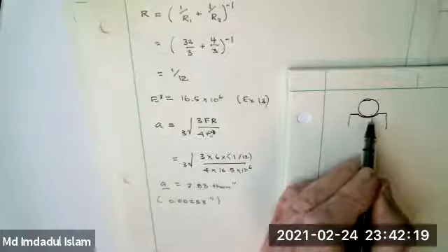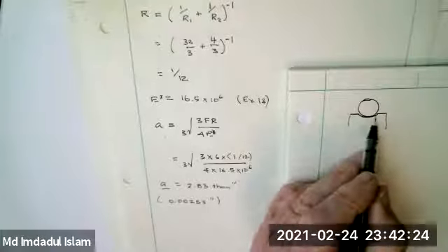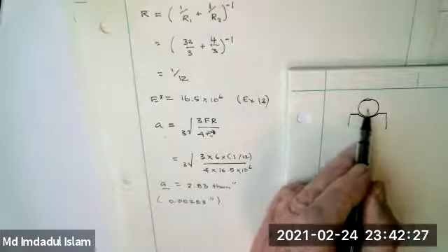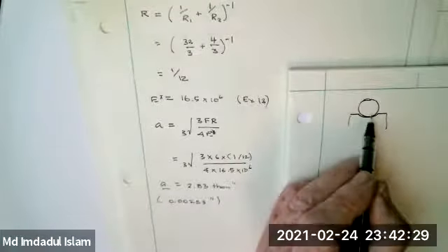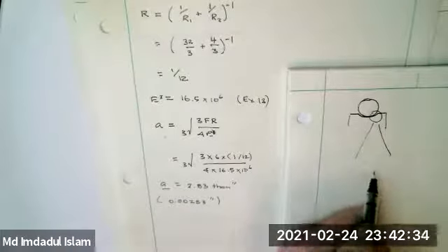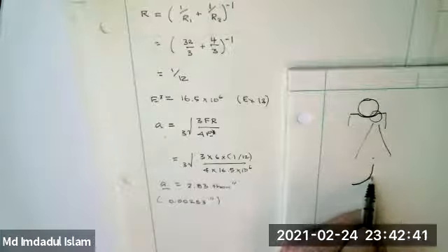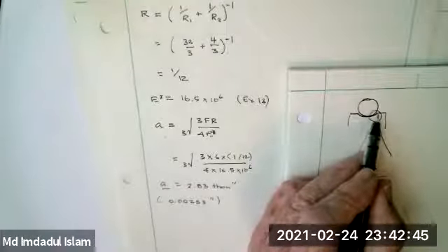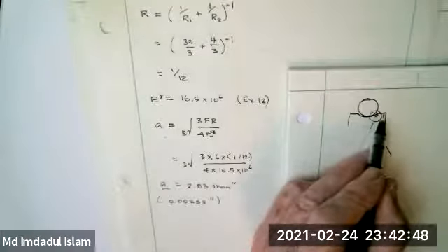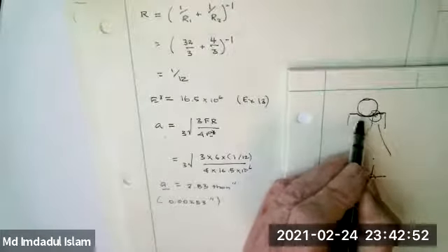Okay, what will happen here is I'll put this groove in, and this groove is shaped with a very similar radius to promote contact. But they'll design this carefully. So what happens here is there'll be a separation before you get to where this thing hits the flat part. Otherwise, you get a high stress there.